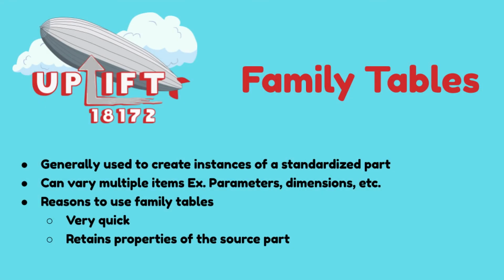This introduction into family tables demonstrates how you can create standardized parts very quickly that retain the parameters of a generic model. There are other, more complicated ways to use the family table, which includes just about any type of feature in Creo Parametric, but this first tutorial has shown how the family table tool would be used in most cases to help your FTC team.